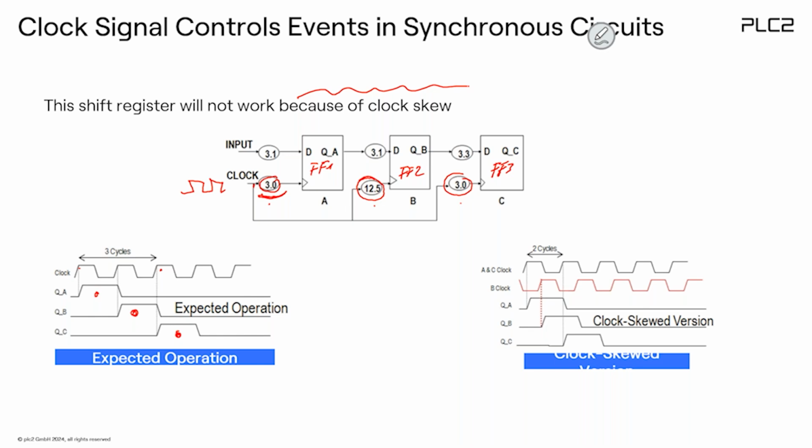It's called a clock skew. It's one signal, but there's a skew, a delay at a different arrival point of the signal. Then you will see it will be completely different. This means at the first clock, the data will be clocked to flip-flop 1. QA will be clocked, but this clock edge is delayed a lot, because it's 12 nanoseconds later. This means the second flip-flop 2 will already clock the new data in. So this means that the function is completely wrong.